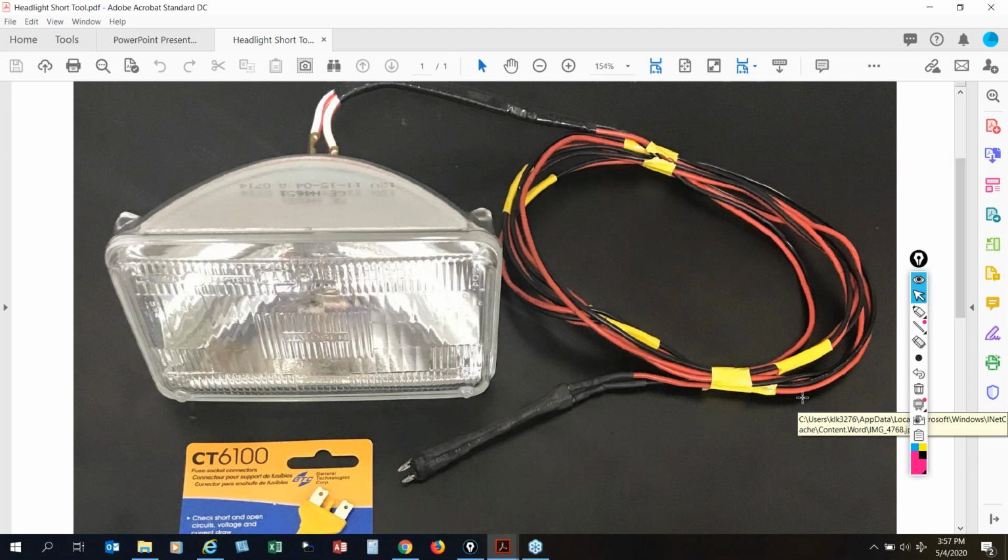Instead of at the adapter end, you just use female spade connectors at that end, and that allows you to change the adapter depending on what style of fuse you actually have to work through your problem with. So just want to give a little information so that somebody doesn't accidentally get in there and damage a vehicle. So great job.